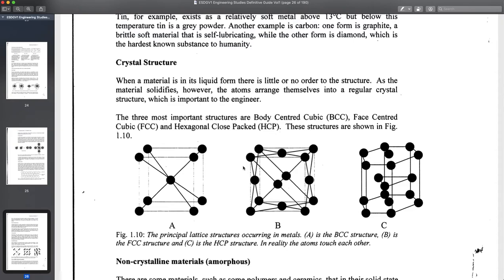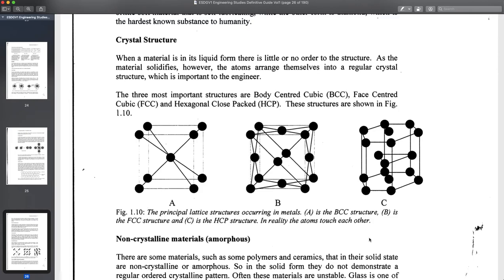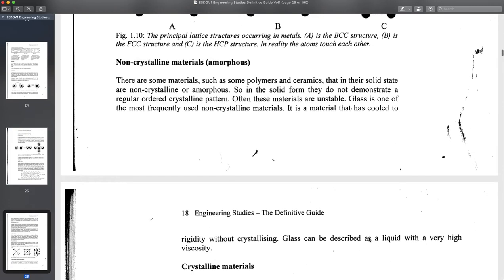What we got to know is that we can stack apples with one apple in the center of every layer, or we can stack apples in alternating layers, where each layer sort of stacks on top of each other, but they're at 45 degrees, right? So this one here is a body-centered cubic, this one is a face-centered cubic, BCC, FCC, and then titanium, it follows a hexagonal pattern. Don't need to worry too much about that. I will never ask you about hexagonal close packs, but you should probably know they exist.